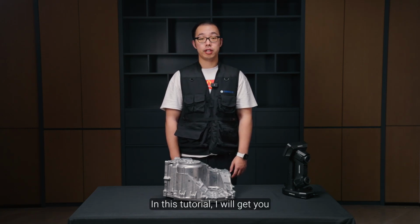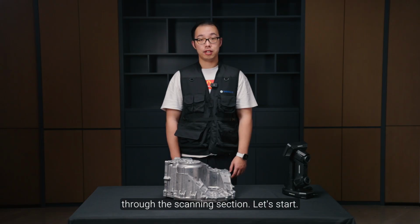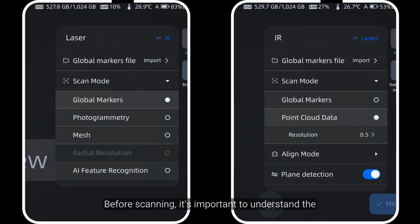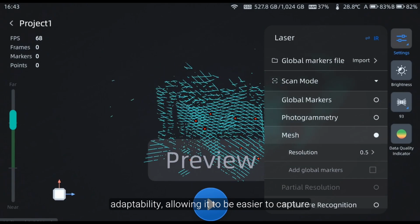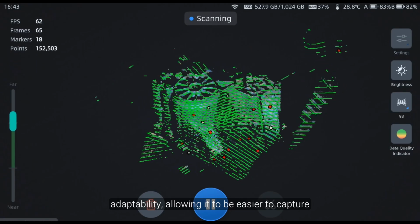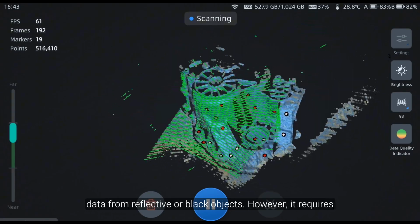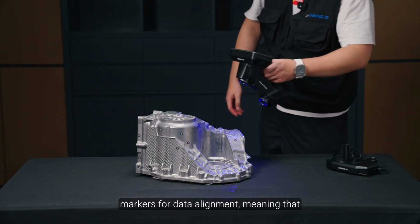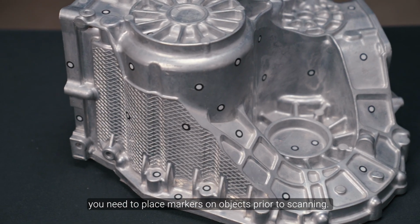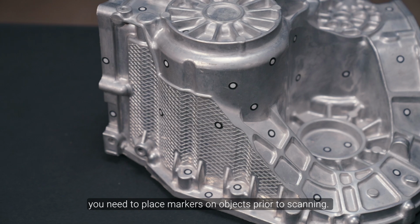In this tutorial, I will guide you through the scanning section. Let's start. Before scanning, it's important to understand the difference between laser and IR modes. Laser mode offers high accuracy and high material adaptability, allowing it easier to capture data from reflective or black objects. However, it requires markers for data alignment, meaning that you need to place markers on objects prior to scanning.